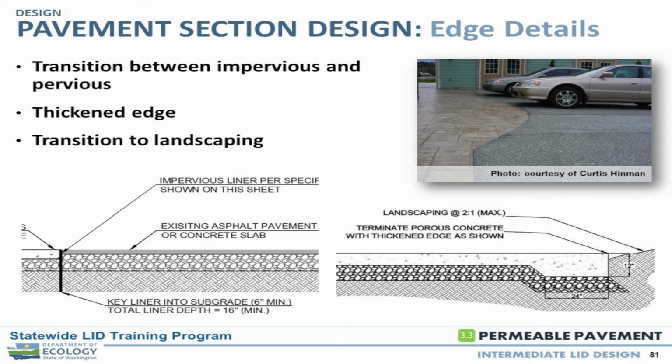But I think at least being conscious about whether you're going to let the permeable base rock flow under the impervious pavement, maybe with a little bit of fabric on there to keep those materials separated if you wanted to have that trapezoid go under. But I think having some sort of barrier is advised, and having that transition be at a crown also advised.